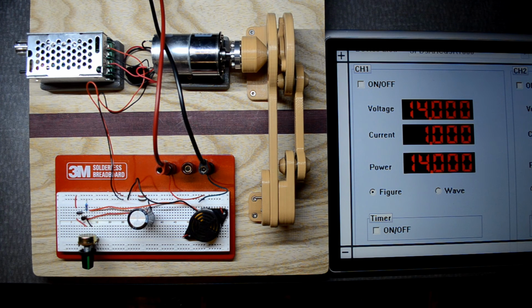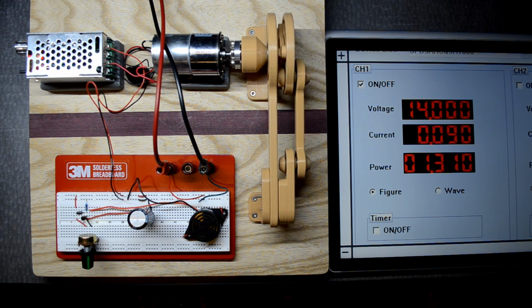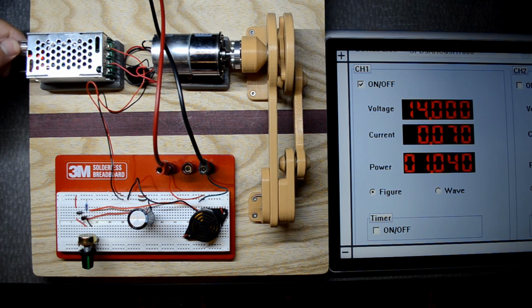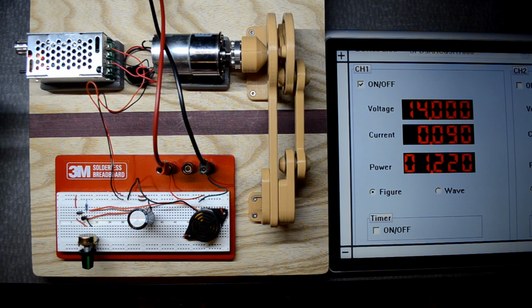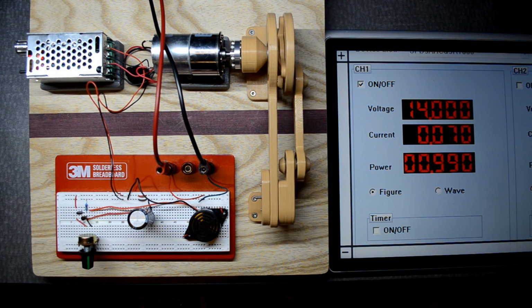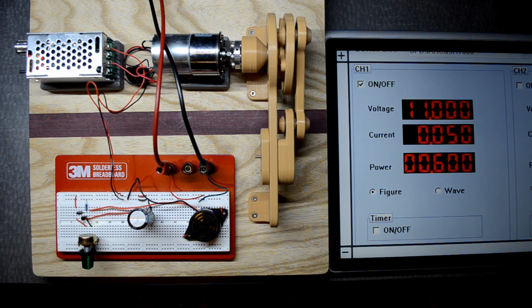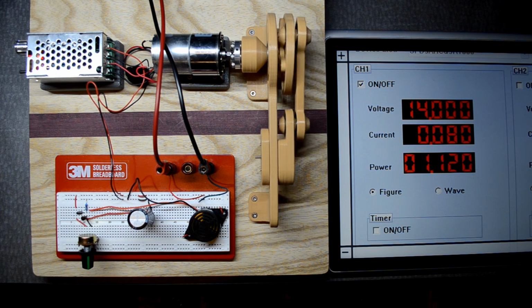This is a demonstration of our power failure alert circuit. At this point, we'll turn it on. We can see the load is running in conjunction with the power failure circuit. The motor itself can be powered down without any worry of setting the alarm off because it is fed power from the same source as the power failure alert circuit. When the main power source has a voltage drop, the alert circuit creates a warning chirp. When the power source has a failure, the charge capacitor drains across the buzzer to alert that a failure has occurred.